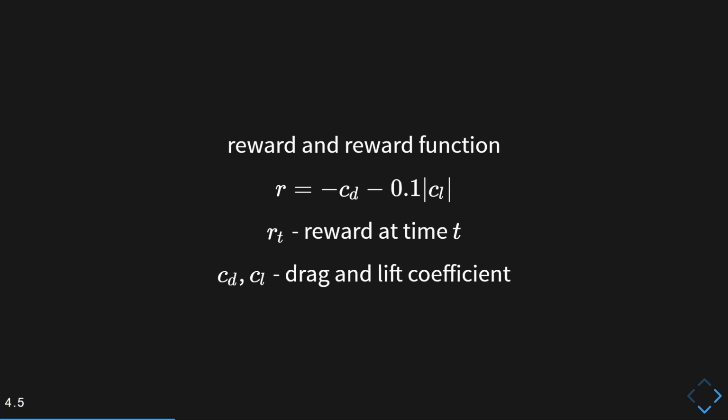Yeah, I would say actually it explores too much. Because if you want to inject some mass, you don't want this mass flow to be a really large number or a really small number. It's much better from the engineering point of view if you can say, okay, I have my engine, I can take that much amount of mass flux away from it, and I can use that for control. And then with the bounded function, you can use this information to say you can inject mass in this kind of range. And from a practical point of view, typically the bounded function learns much quicker, by a factor of maybe 2 to 10. But on the other hand, of course, you have to think about sensible control bounds, which is one thing that at some point you definitely should think about anyhow.